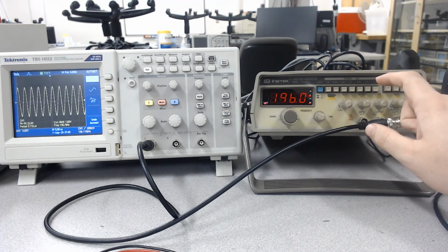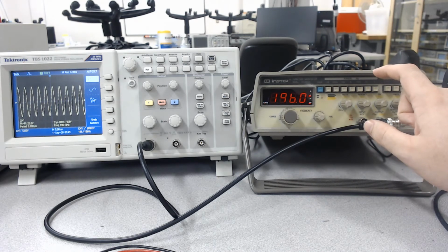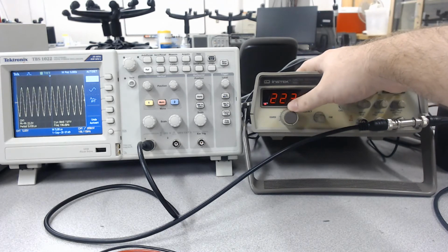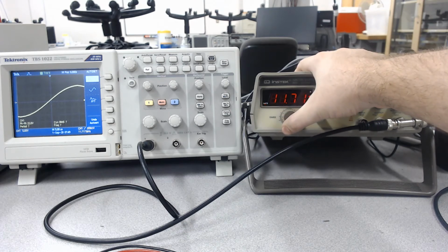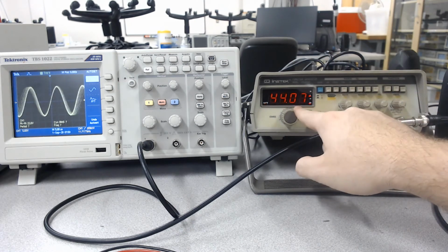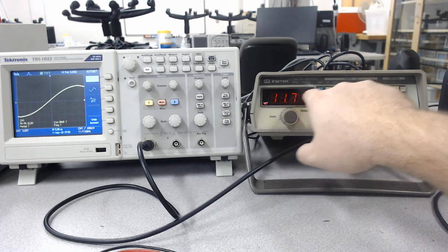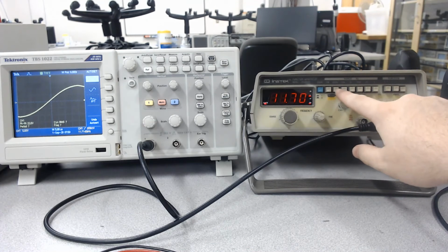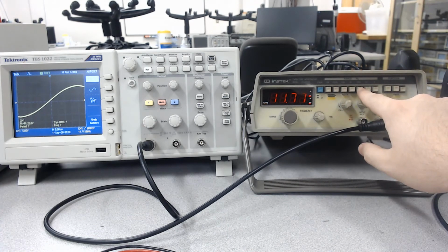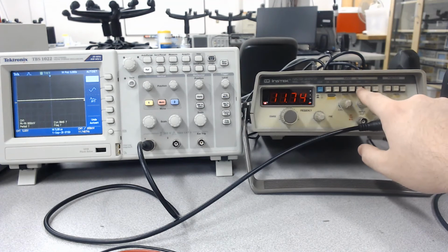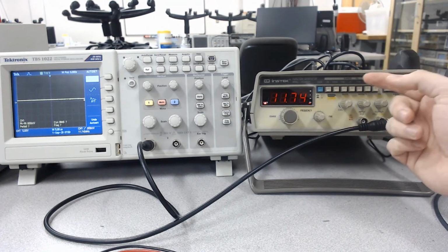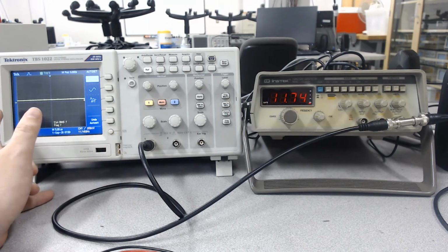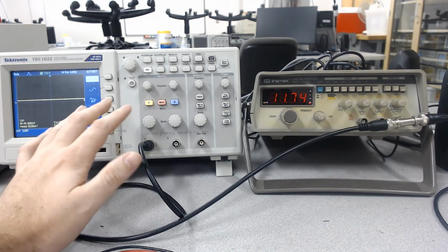We want 100 hertz. So ideally, we're just going to go right to this knob and twist it. You'll note that even at the lowest I can get, it's 11 kilohertz. So that's not good. The way to fix that, obviously, is that I am in the 100K range, and I want to be down nearer the 100 hertz range. So if I hit that button, you'll note that the oscilloscope went completely flat. That's because the frequency has drastically dropped.